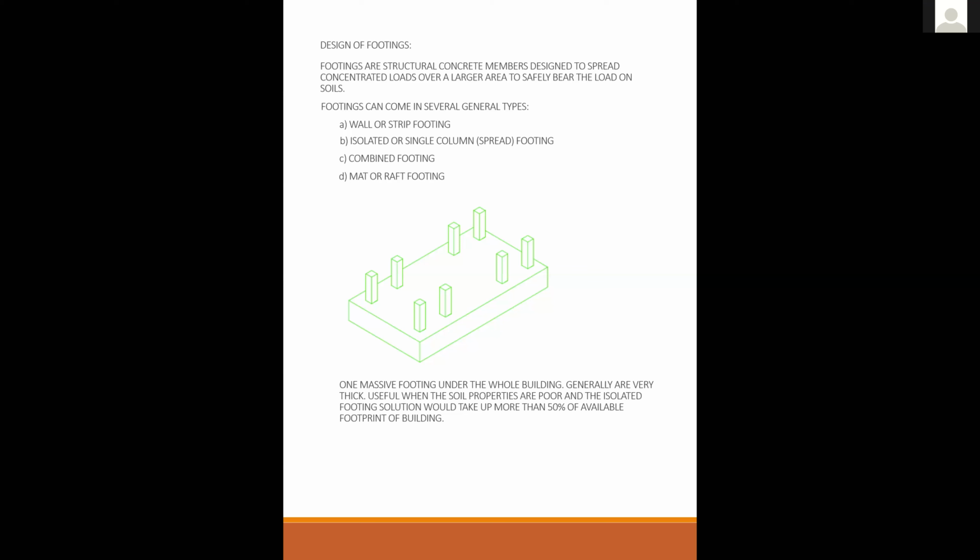Yeah, because my senior project advisor, because we were modeling a slab on grade, however the program that we were using only offers a mat foundation option. So he basically just instructed us to treat the slab on grade as a mat foundation and just do what the program does. Okay, no, I understand. So basically, you did a really thin mat foundation.